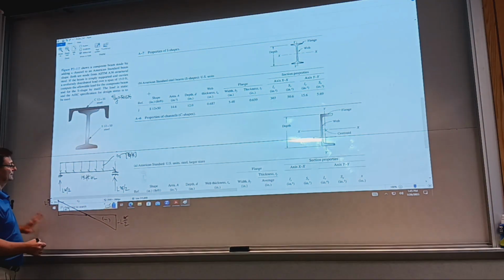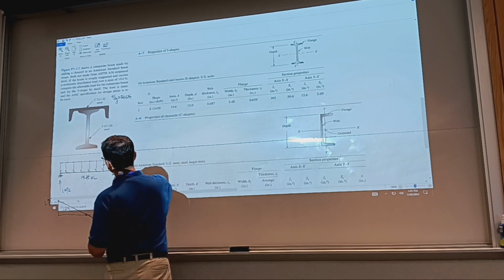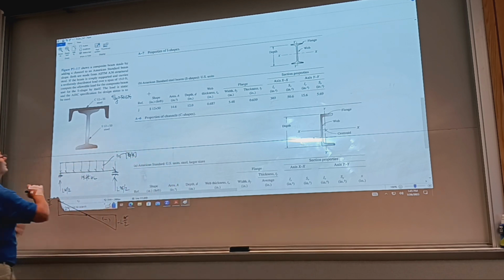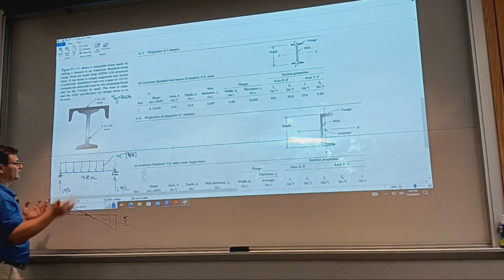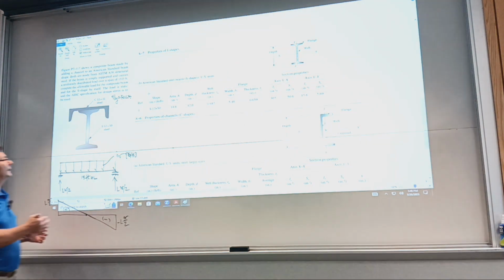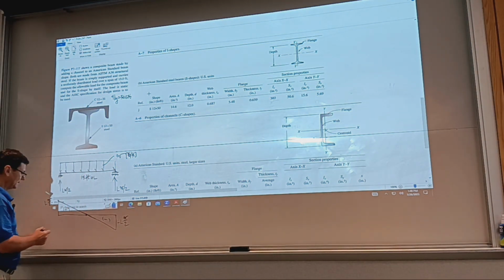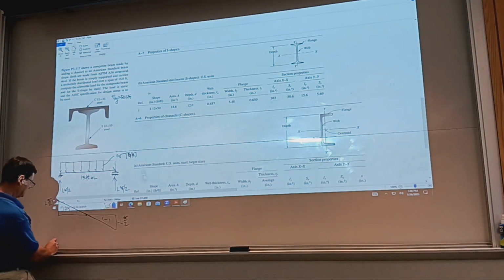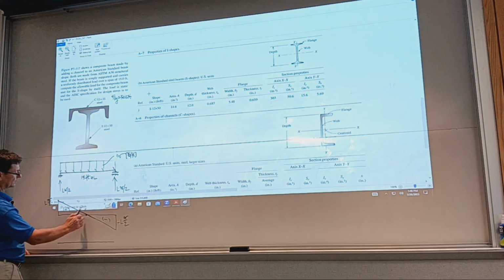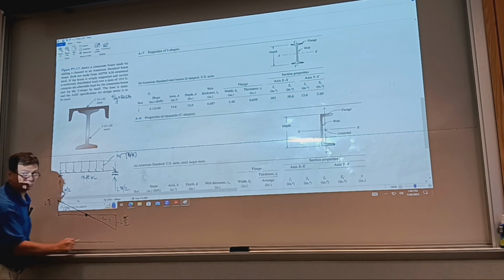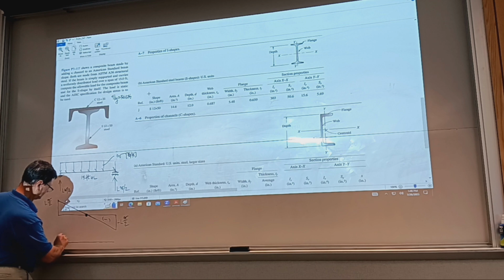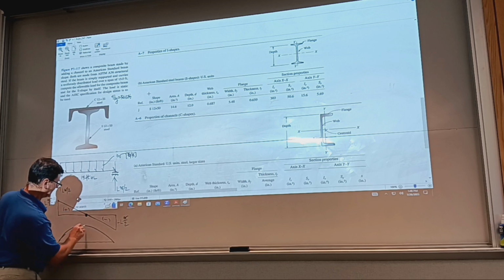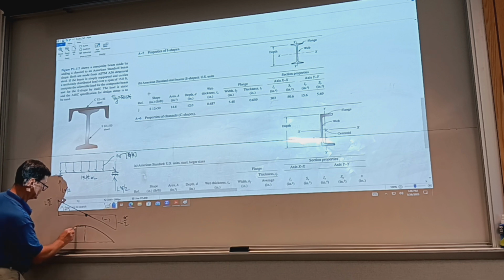And then I'm forced to move the moment diagram elsewhere. The beam is going to be smiling, so the moment is all going to be positive. I can squeeze it here, no problem. The moment diagram is going to be parabolic: it starts with a big slope, goes to slope 0 in the middle where the moment is maximum, and goes back to 0. It's an inverted parabola, and the maximum of the parabola is at the middle.